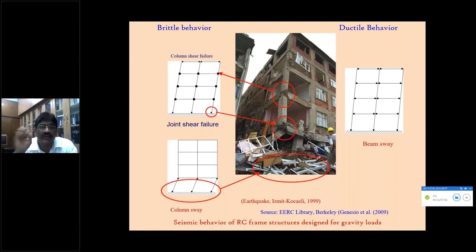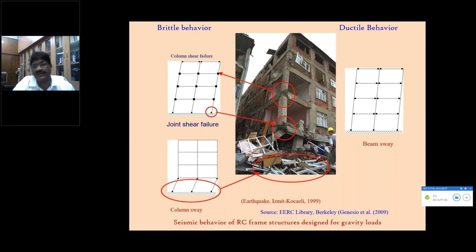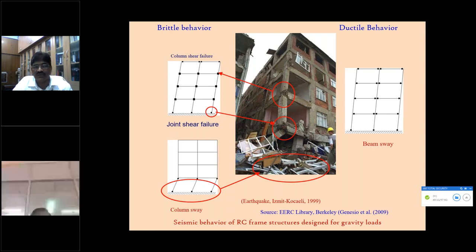We have to analyze the system, calculate the bending moment and shear forces. In the existing building, for the existing element, you know the reinforcement details, the sectional dimensions, the materials, and calculate their capacities, either bending moment, shear strength or flexural strength. And you compare with the forces acting, bending moment, shear force, or any other force acting. That's how we do. Any building, we can model in the computer and assign the design loads, including now earthquake loads.